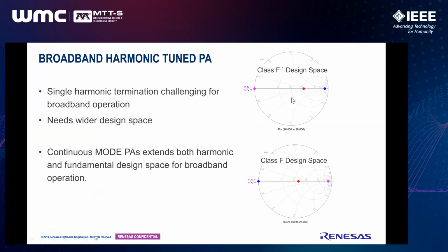This single termination is good for a single frequency of operation, because when frequency changes, of course, the impedance termination is going to change from either open or short circuit. So what should you do? That's how continuous mode PA was introduced by Cripps and his group.